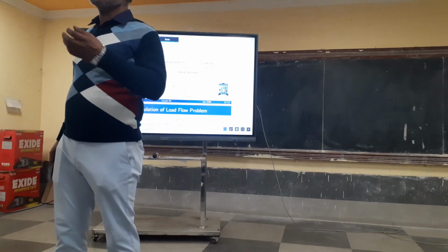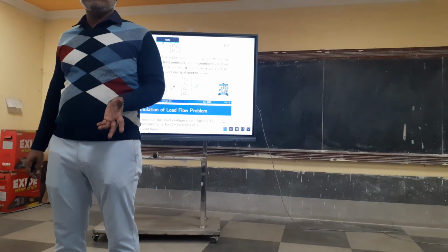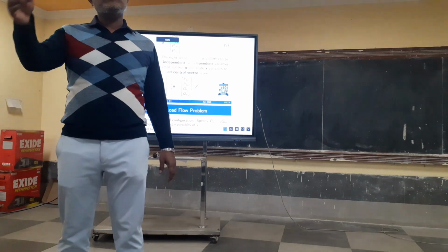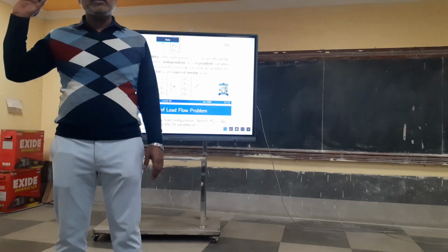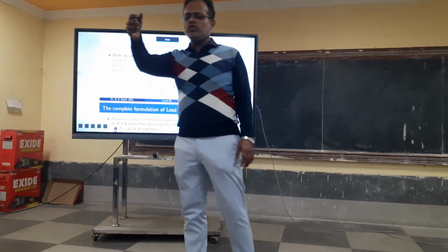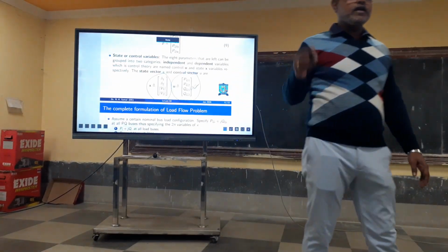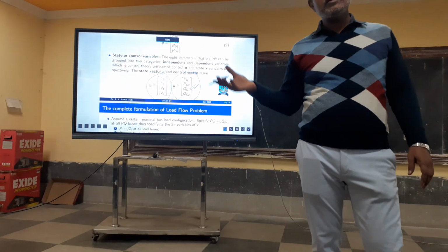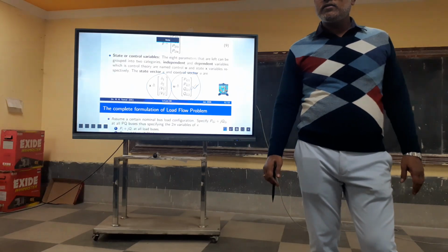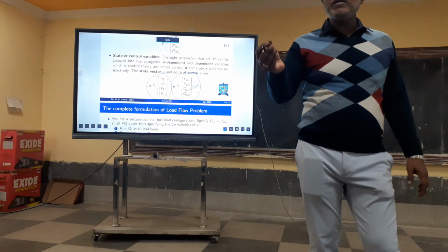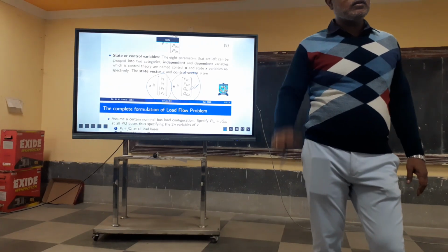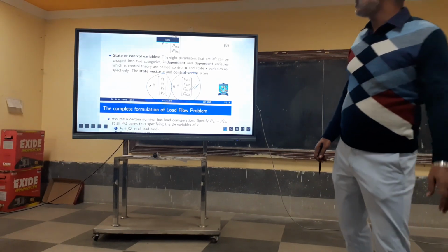We can change the generation of a generator depending on the demand. Just like I told you, as he rightly said, we forecast the load. So we forecast it to be 300 megawatt. The SLDC, the Odisha State Load Dispatch Center, estimates that it will be 300 megawatt at a particular time. Now suppose it becomes 302 megawatt. What will be done? Nothing. You will just make minor changes in the generators. Mostly the fast generators will provide it, or spinning reserves.